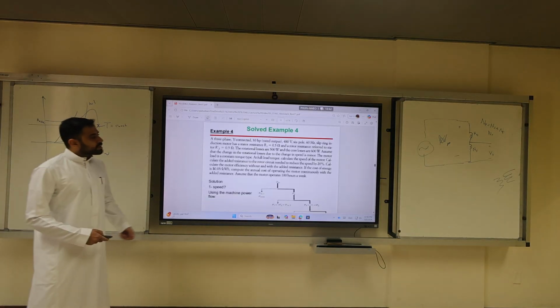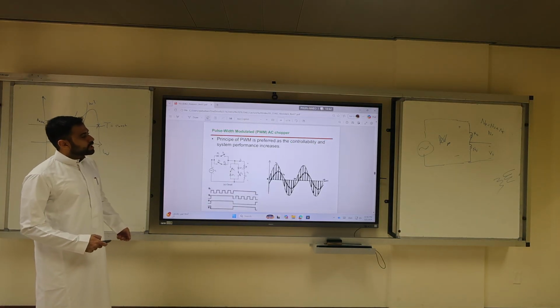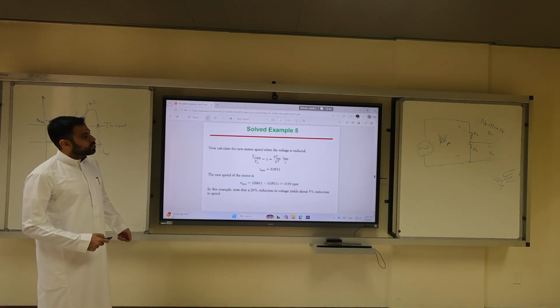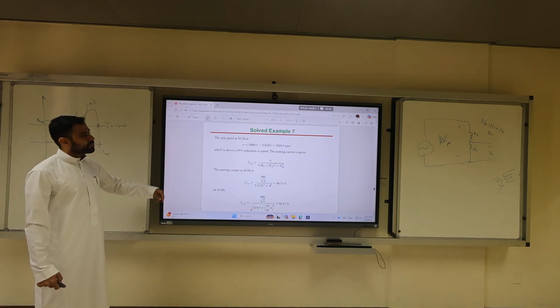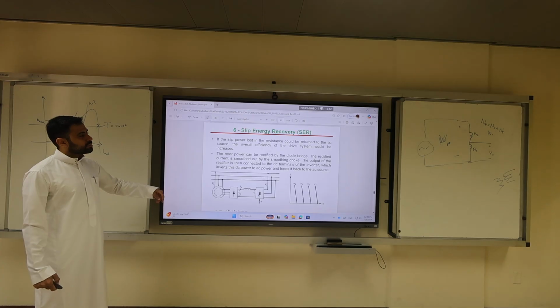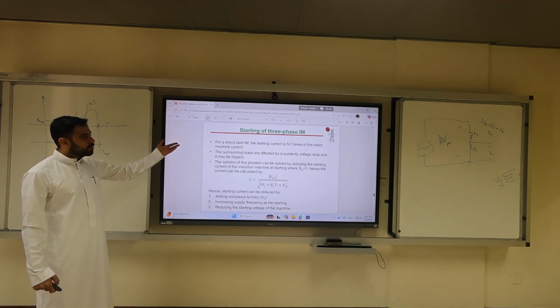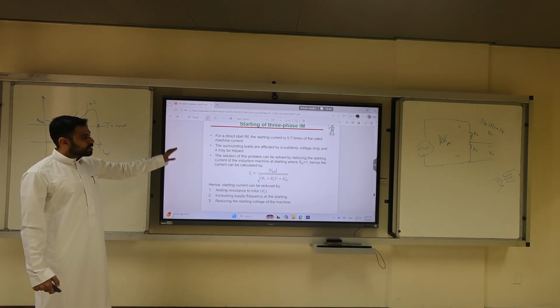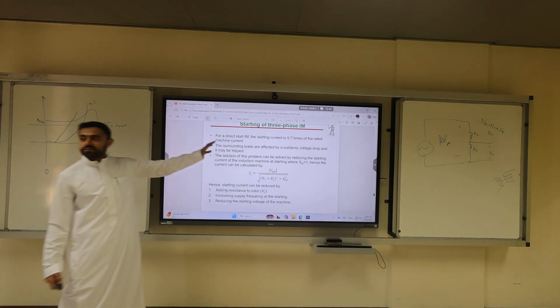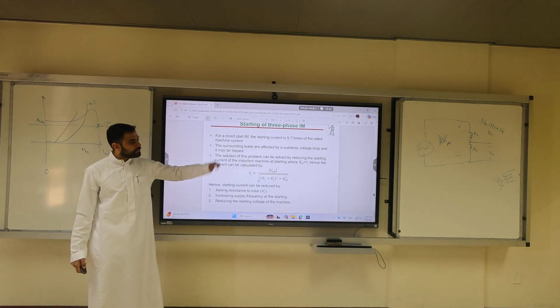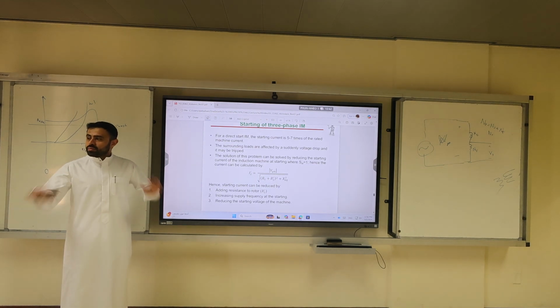So today we covered, what did we cover? Let's review it. We covered the starting three phase. We said the starting current is always 5 to 7. Anything higher is bad. And if you know nothing, assume it's 5 to 7.